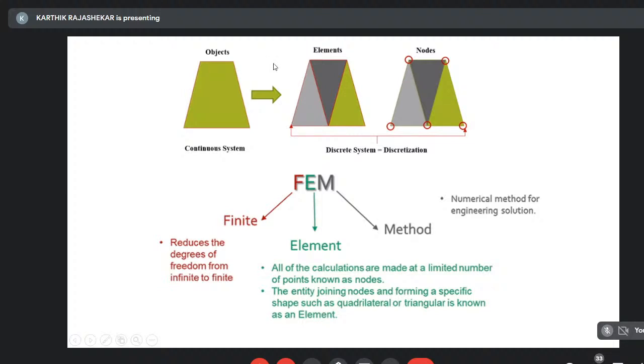So whatever the object you have, whenever you say that you're trying to mesh your model, it indirectly indicates that you're trying to discretize the given system into known number of parts. So here I've discretized my given system into 7 parts. So I can see my 7 elements. And again, remember each element is surrounded by a node to one end, a node to the other end. So you can see the number of nodes over here. So each element, say for example, if I say I have 1 element, so 1 element has how many nodes? 2 nodes. So if I have 2 elements, then it has 3 nodes. So in the similar way, if you can look into this given figure, I have 5 nodes over here.